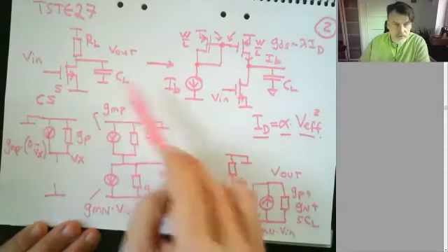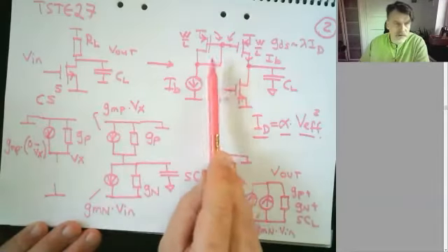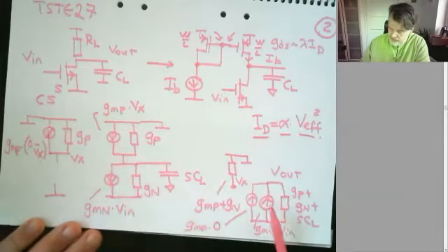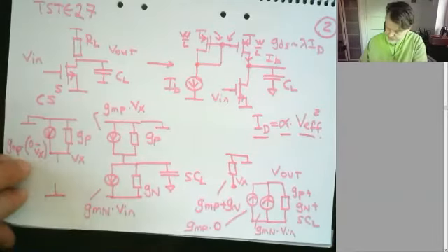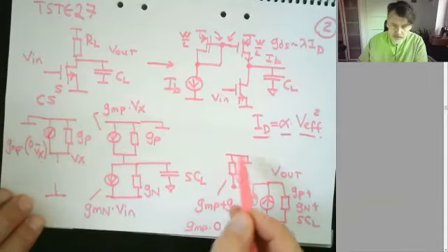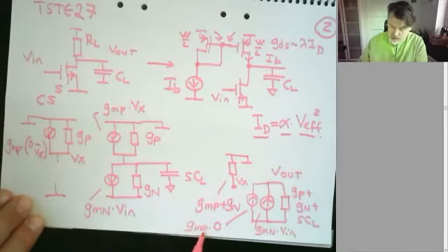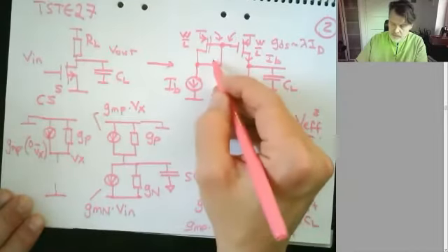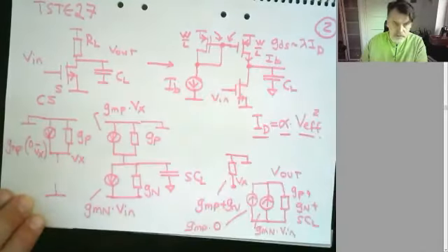So from this first order analysis, this current mirror does nothing to the small signal characteristics. If we take this one step further, this guy just floats around on the left-hand side. The GMP times 0 does not accumulate anything from the current mirror side to the output.